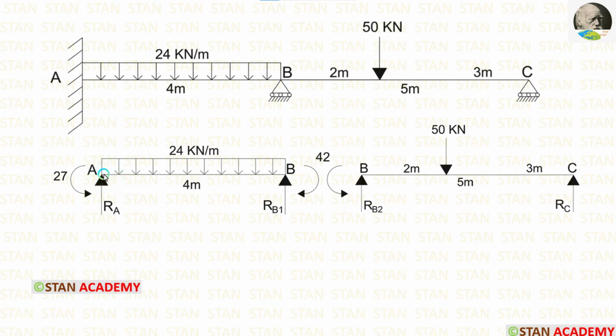In the span AB, there will be two moments. MA will be acting in the anti-clockwise direction. MB will be acting in the clockwise direction. In the span BC, there will be one moment. MB will be acting in the anti-clockwise direction.